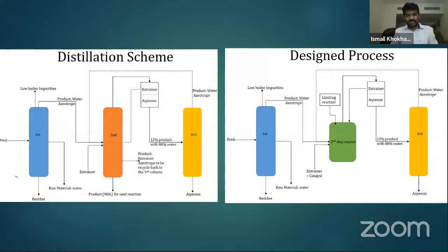So as a process engineer, as I told you, before using methods like McCabe-Thiele or the FUG method or any other distillation method which you have studied, these are the hidden factors which you need to evaluate to understand the dynamics of the distillation column. Because as I keep on focusing, the impurities that are generated have a major impact. The impurity had changed the dynamics of the distillation column, because it was forming an azeotrope.